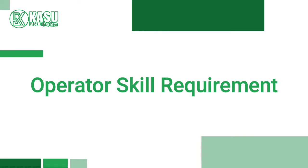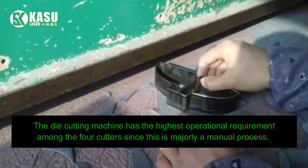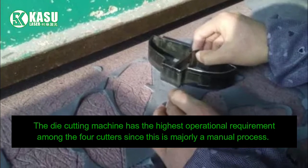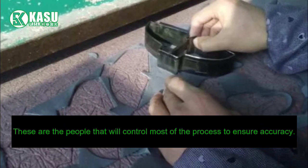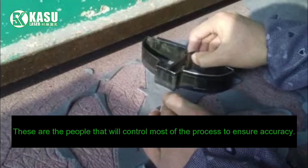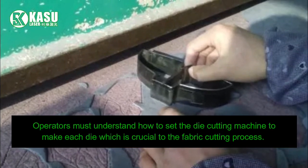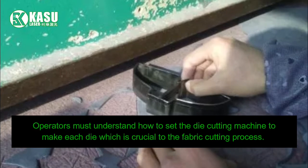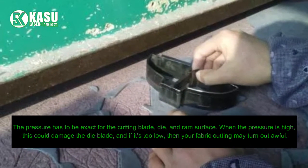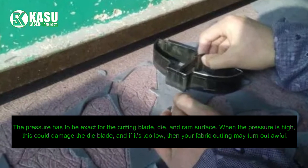Operator skill requirement. The die cutting machine has the highest operational requirement among the 4 cutters, since this is majorly a manual process. These are the people that will control most of the process to ensure accuracy. Operators must understand how to set the die cutting machine to make each die, which is crucial to the fabric cutting process. The pressure has to be exact for the cutting blade, die, and ram surface.